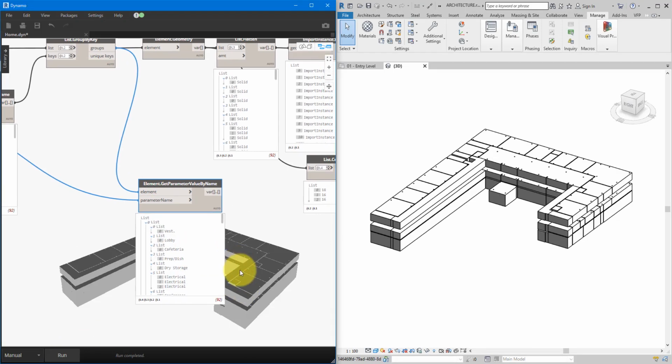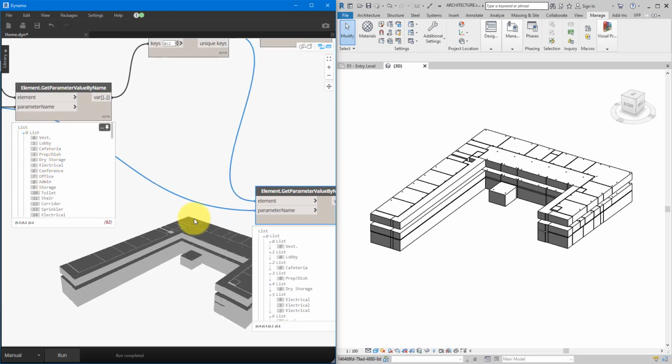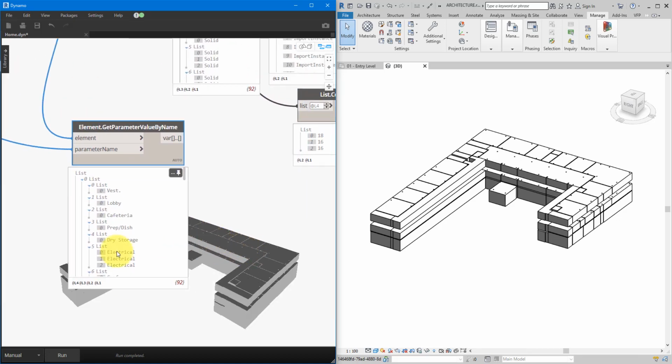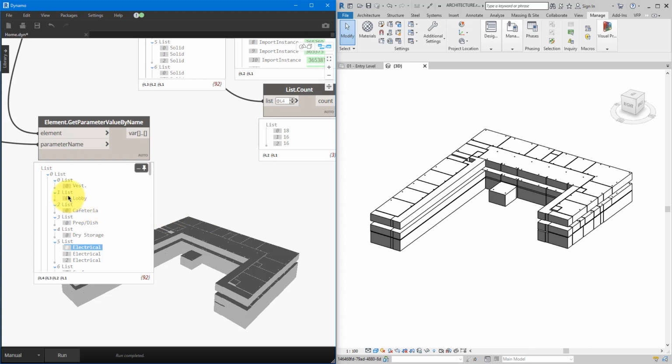Here we go. Now, instead of just a flat list of names on each level, I have actually names of the same value in a list, and then several of those lists under a level. So that's a level category, then the list of names, and then the names in each list. Next step, I want to make sure to get only one value per name per level. Let's think about this. These 3 rooms here, I want to give them the same color anyway, so there's no point having the same values 3 times. The same goes for something like further down, like instruction there. All of these 5 rooms can get the same color based on the name of instruction.